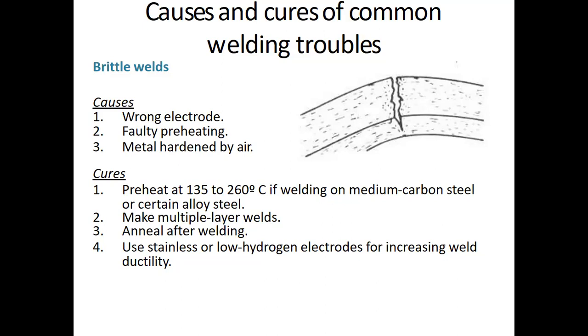And after that, once you put off the furnace, you allow it to cool down inside the furnace. So that's annealing. That will release these stresses, so this brittleness will reduce. Increase the temperature and cool it in the furnace itself.